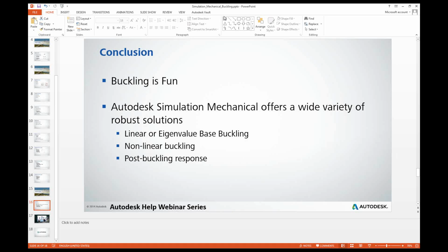One of the things that you may consider, like Marwan showed in his model, we're looking at that plot. Sometimes that break between the axial and bending stiffnesses is not as clear. You may not have that sharp break. It's more gradual, so it's difficult to see or interpret when that critical buckling load is.